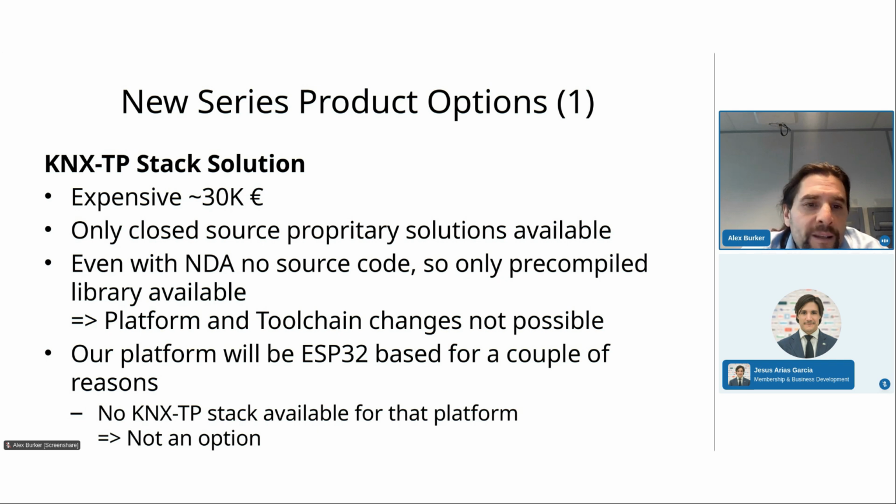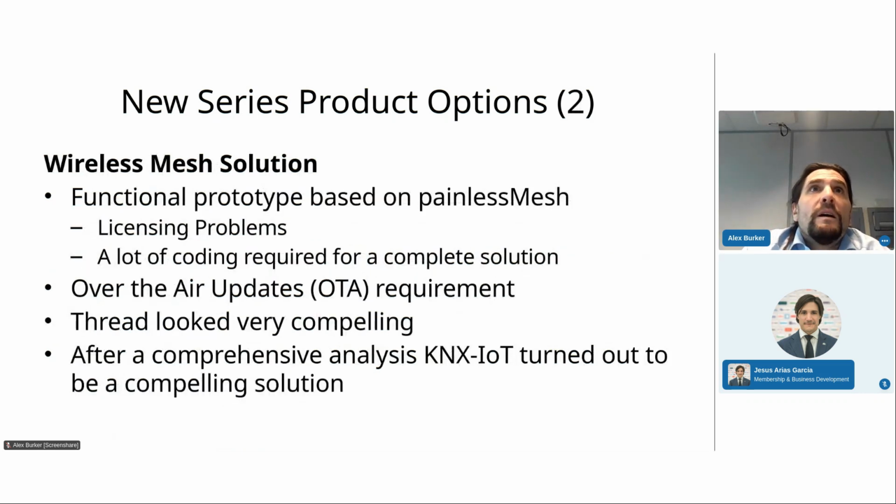And the problem is there is no existing solution, which I know of, that could work with our ESP32s. So this was not a good route, and we had to find a better way to do it. So we decided to go for a solution that works wirelessly in a mesh. The first thing we tried out was a mesh network with a proprietary solution from Espressif for the ESPs we were using.